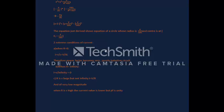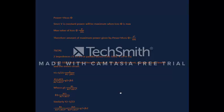Let's also see the extreme conditions of current. When R = 0, I = V/Z, which is also equal to V/X_L. Therefore, power factor becomes 0. It's a purely inductive circuit. When R = infinity, I = V/infinity, which is obviously 0. And also the third case, R very large but not infinity. In that case, I = V/R at a very low magnitude; when R is very high, the current value is lower but power factor is unity.